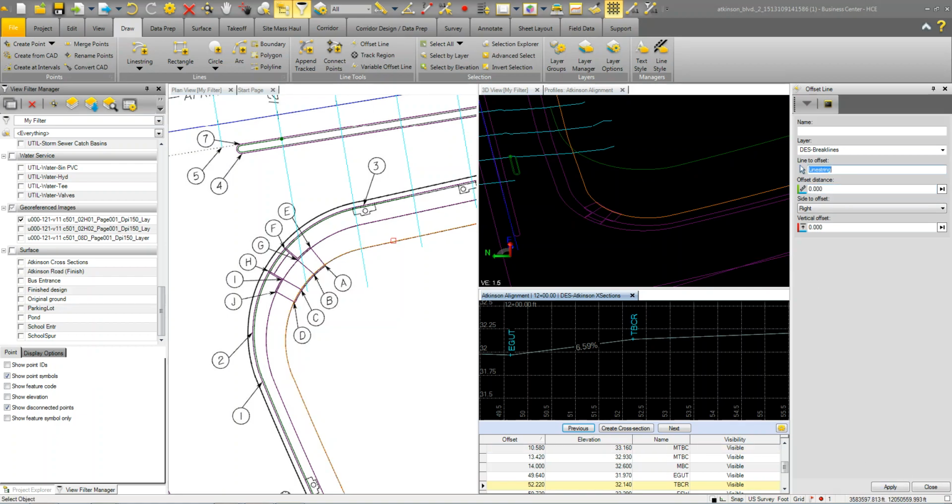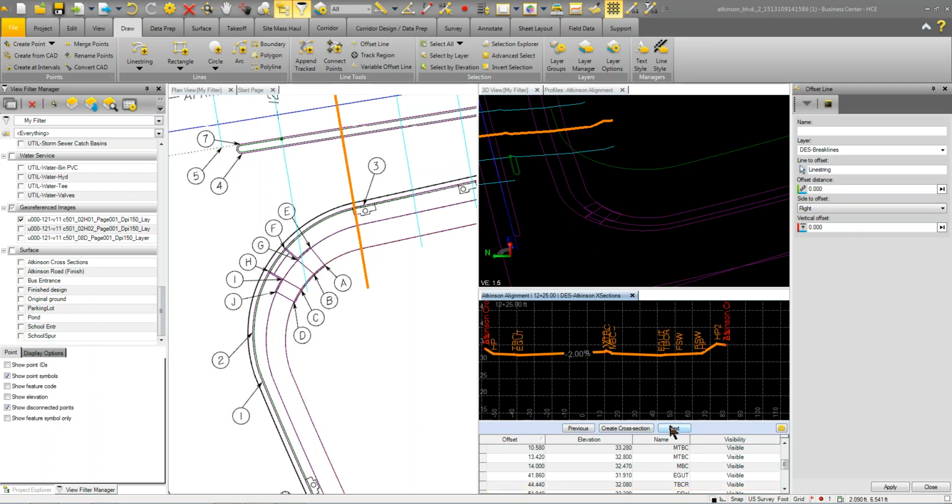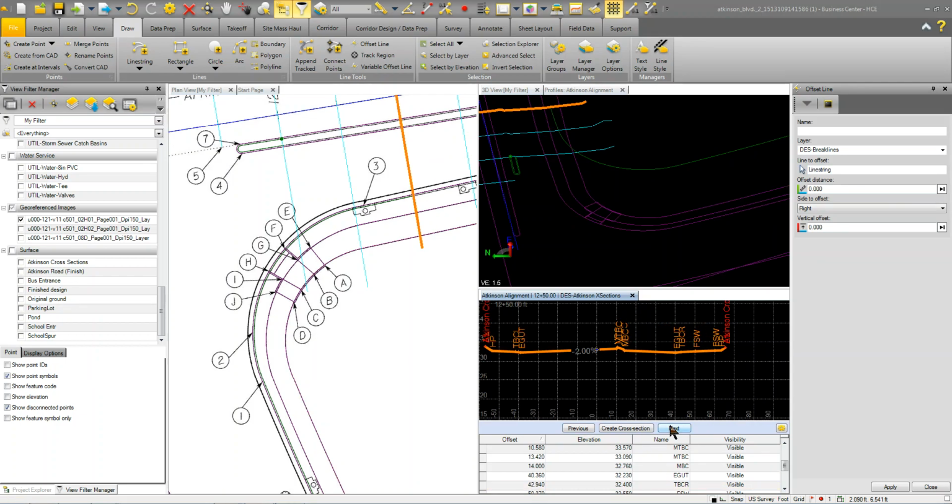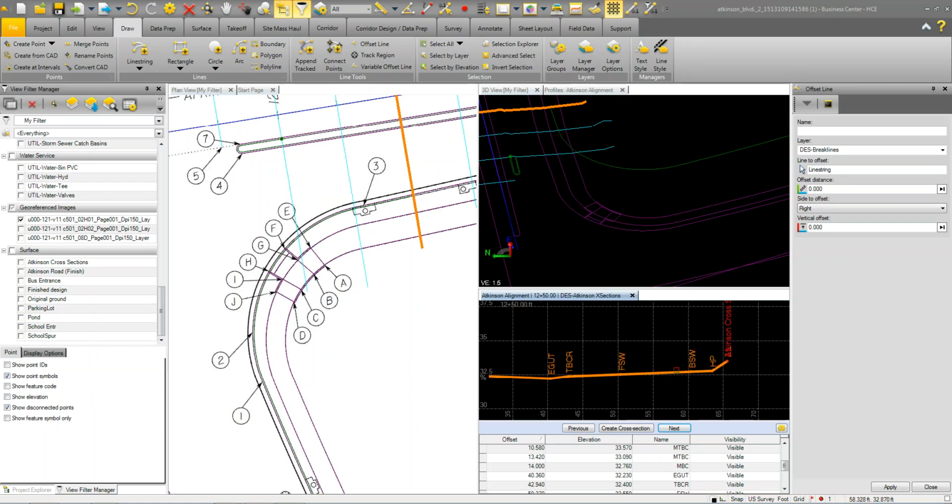And I don't need to go all the way back with this. I can kind of keep it here if I wanted to. But if we go back, let's say next, take it all the way back to here, then we can see we do have a sidewalk that we can tie into. So we can make sure that we tie in properly to that sidewalk. So we would just repeat that process, the same thing we did on that curb line all the way through here.